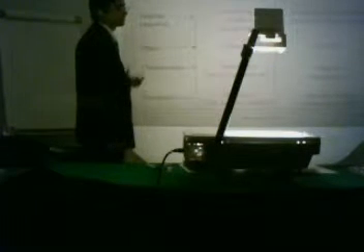And what are the characteristics which we are going to audit? Dimensions, surface conditions. On what basis we are going to check the dimensions, that is parameters, sequences, everything. And what are the documents which will be supporting us so that we can audit, that is drawing, technical supply conditions. Based on this, we will check machine setting and maintenance plans. So that is a comparison of process and product audit.